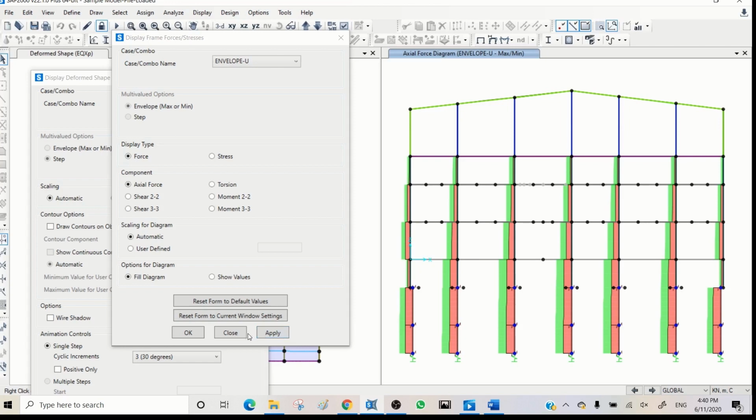You need to thoroughly check the modal deformation, the deformation due to gravity and lateral loads, and internal forces. You need to see the logic behind transferring load. If you don't have such a step increase in load and suddenly something is missing here, that means there is something wrong.